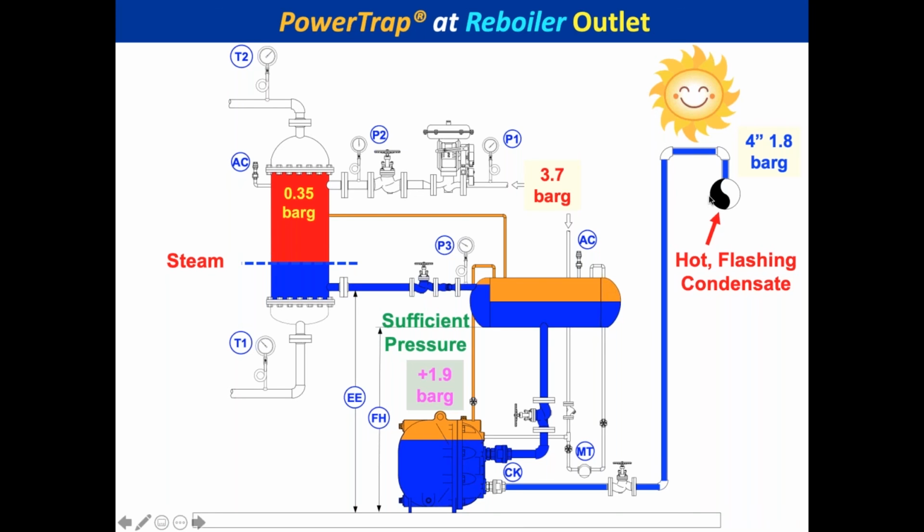And if you had the line down to make that entry point, it's not a lot of condensate. I mean, a couple thousand pounds. What you could do is put 3 or 4 entry points of small bore diameter, 5-10 feet apart. So you're mixing the condensate from this line into that line at several locations along the line. You'll get it in there because you put blow valves in there to adjust how it goes into that flow, and that would mitigate the hammer, and that would save you installing 800, 1,000 feet of 2-inch pipeline. And that's really the goal, to recover the condensate and not have to install 800 to 1,000 feet of pipe.